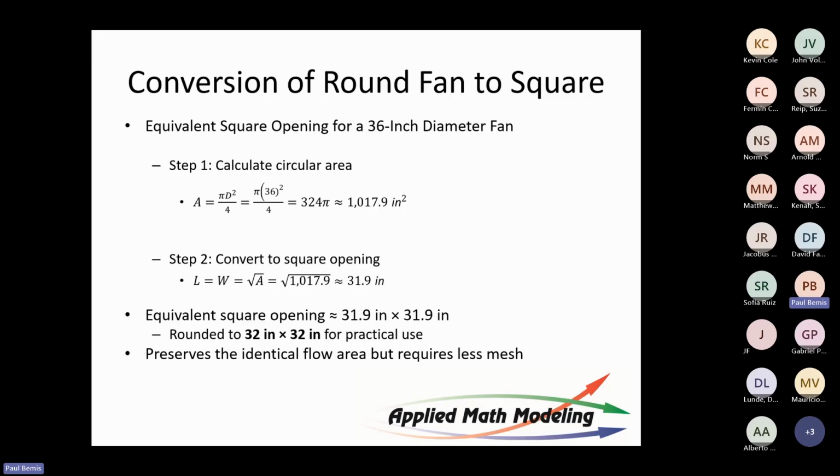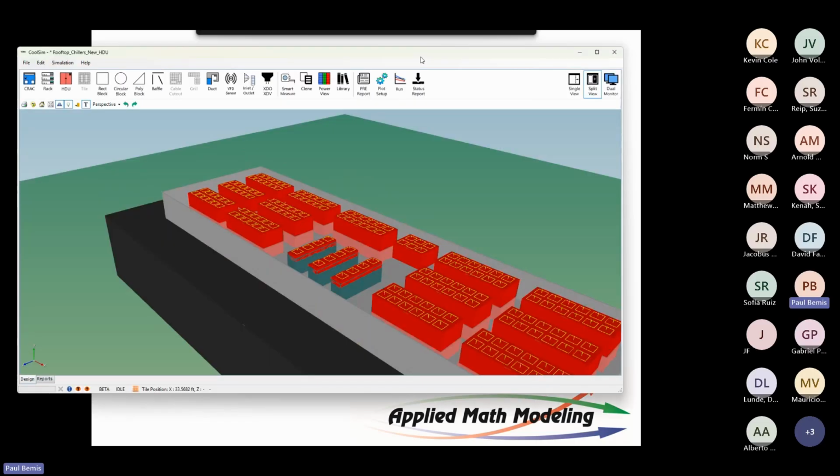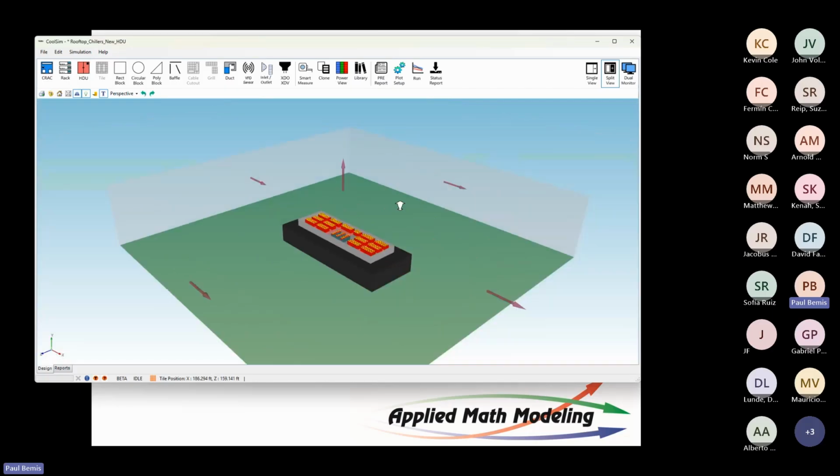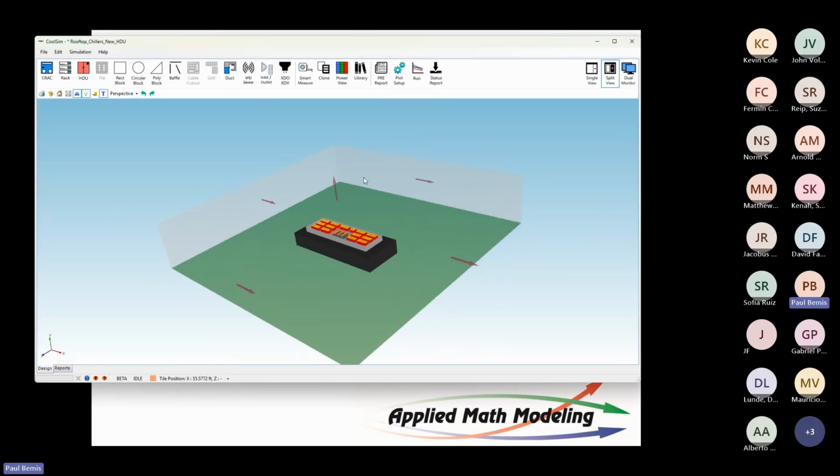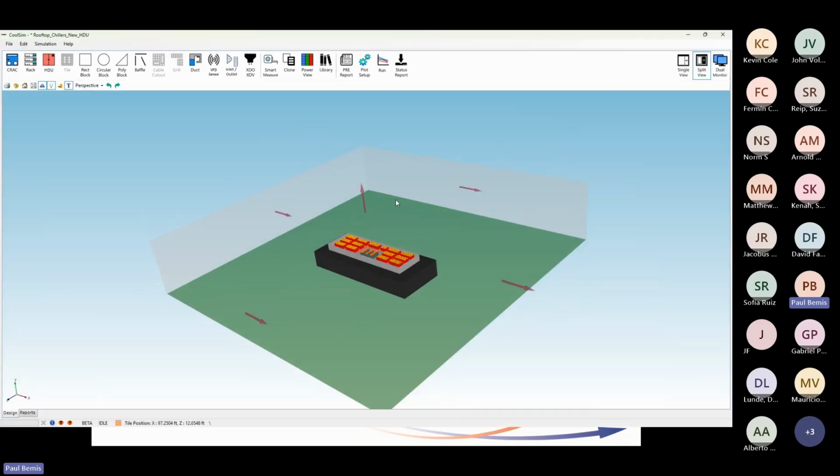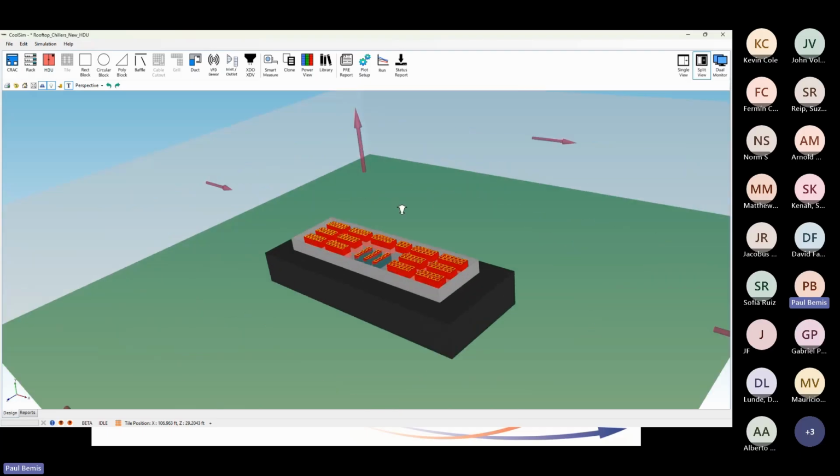So the way CFD works is we take this entire environment that I'm showing you here, defined by this box, and this is called the bounding box, and you can see airflow direction. So this one's got air flowing straight across it. And we break it up into a mesh. A mesh, you can think of it as a polygon. Here we're hex dominant, so it's a hex structure, polygon, three-dimensional. On every surface, we do differential equations to calculate conservation of mass, momentum, and energy.